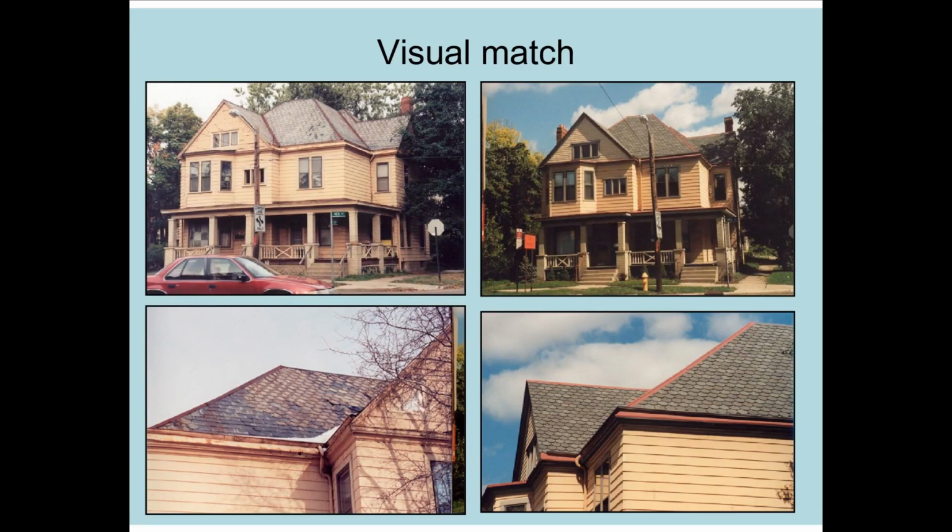Similarly, a polymer-based slate substitute may match the thickness and surface texture, but only be available in a larger size than the historic slate. Before the appropriateness of either substitute material can be evaluated, the characteristics of the historic roof that are most important to how it is perceived on a particular building must be identified. This may lead to choosing one substitute material over another, or rejecting all if the resulting difference appears to be too great.